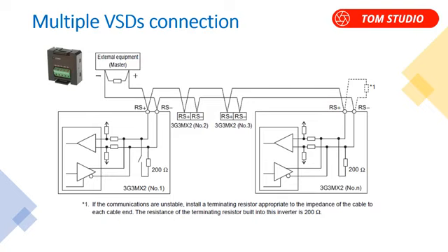If you are looking for fast speed or motion control, Modbus RTU communications is not a good solution. You might think about EtherCAT, EtherNet/IP, etc. Industrial Ethernet solutions are far better and faster than Modbus RTU serial communications.